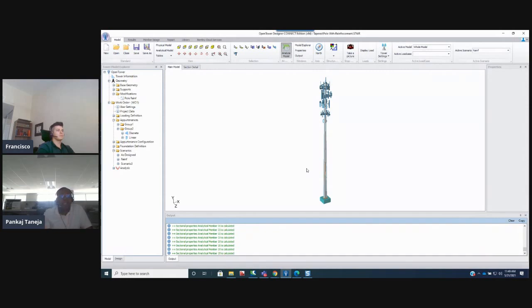There is no standard database available in the market, right? You can create it. So what we did is we calculate the section properties for each analytical member at this point, and you will see that sometimes it jumps from 46 to 40, and somewhere you will see that it goes back to a different number because now it's calculating the section properties at the plate level which we entered